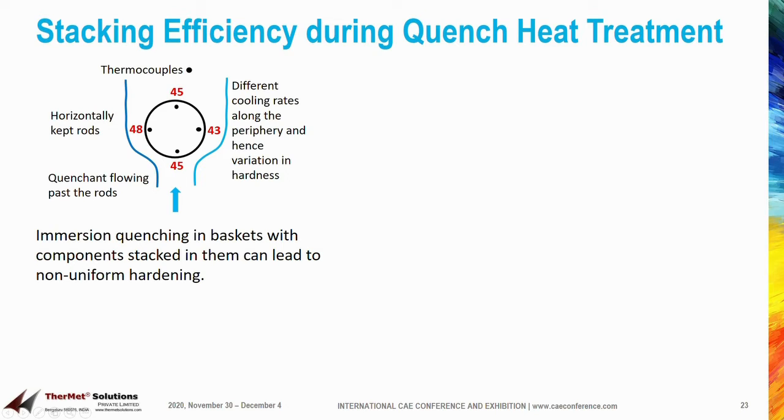A test rig was designed to collect the time temperature data during heating and quenching. 4 thermocouples were inserted 90 degrees apart, 5 mm below the surface along the periphery of the rod.